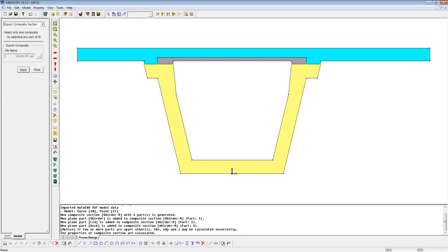Great. Another question is coming in. Can we use rigid links instead of dummy elements? Rigid links shouldn't be used because they are infinitely stiff, and what they really do is they transfer entire load from one source to another, which is not the true behavior of the deck, because at any given time the force is being transferred with the member whose thickness is this much only.